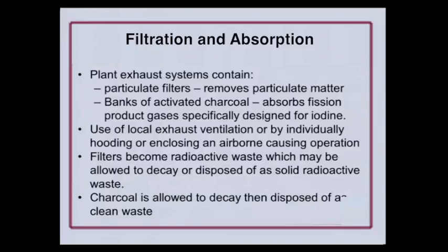Toward the end of the outage period, when you're getting ready to start back up, they'll do core samples of the charcoal and analyze it for radioactivity, and typically it's decayed such that it can be handled as non-radioactive. Because the half-life of iodine-131 is what? 8 days. A little bit more than 8 days, so it doesn't take much.